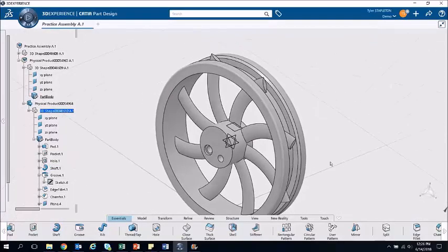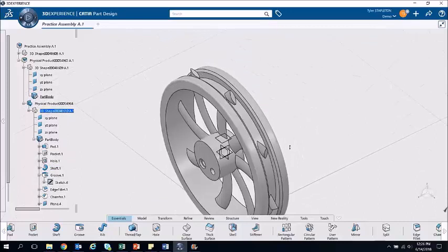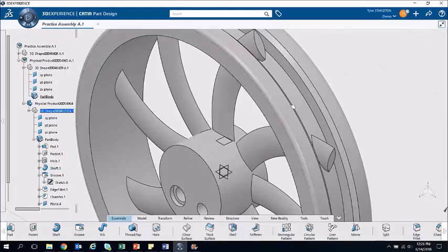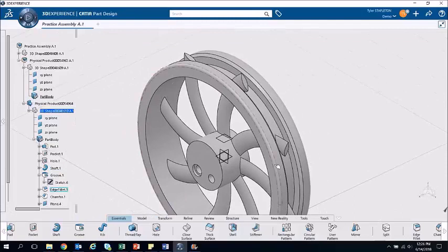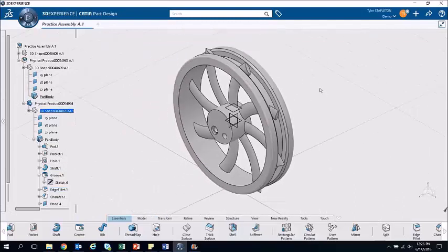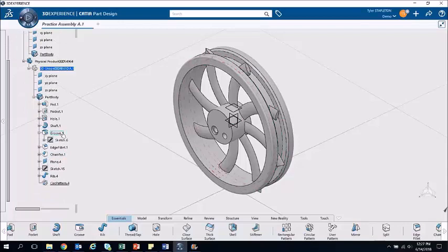Alright, so let's come back to these little spikes that are sticking out the sides. We don't want those, so we need to figure out a way to get rid of them. I could come through and remove this material myself, but what I actually want to do is just reorder my tree here so that this groove that we cut comes after that pattern that we just set. In order to do that, I need to select the groove as well as the fillet and the chamfer, so I'm going to hold Shift and click on that chamfer.